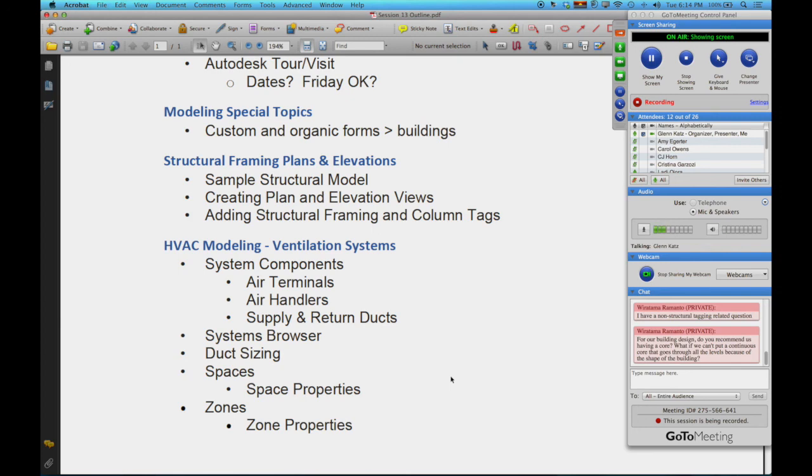Now, if the design of your building is such that you can't put one going all the way up, that's fine, as long as we take care of the stairs, getting them all the way up and down. For the lateral reinforcement, if we can't do it with a concrete core, we just need to think about doing it with a bracing system or some other system that'll let us transfer those loads all the way from the top down to the bottom.